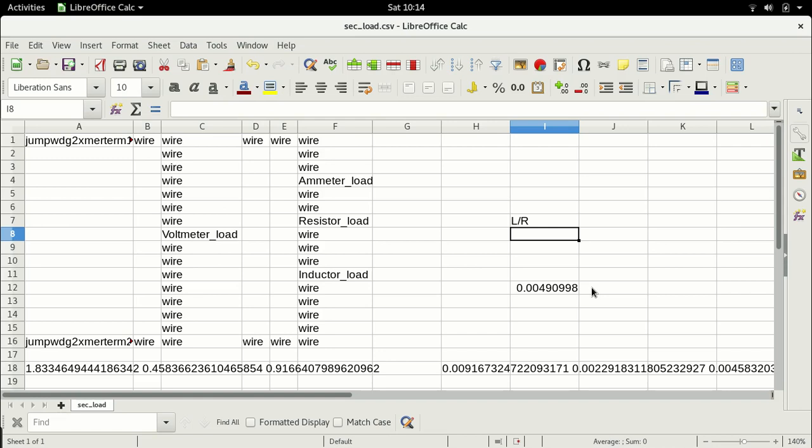And when the circuit is prone to faster oscillations, the result is you have to simulate it much faster in order to be able to achieve a stable result. That is what has happened, right? So what this means is we are not simulating our circuit fast enough, and that is the reason why this circuit is becoming unstable. In the previous case, when we simulated a 50 Hz transformer subjected to 10,000 Hz, in that case we didn't have instability, we had an error. But now we have downright instability because our system is much faster, right?